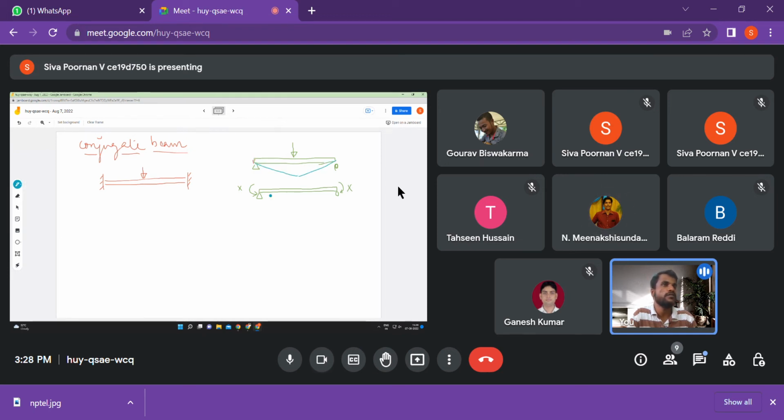And for the second case, it's a rectangle, a perfect rectangle, and I'm putting it down just for space convenience. Or if it's confusing, I'll do this as positive, top, and this is bottom. One is negative, one is positive. As you can see, one will sag and one will hog. So this is the bending moment variation, right?